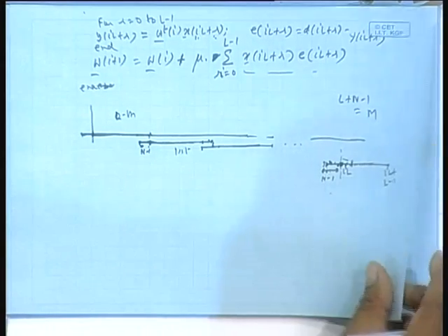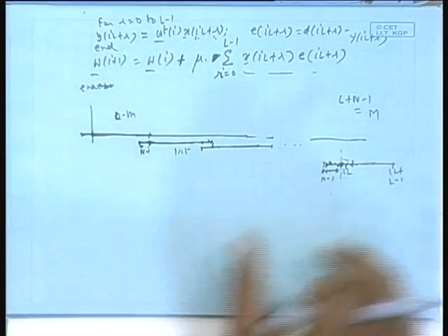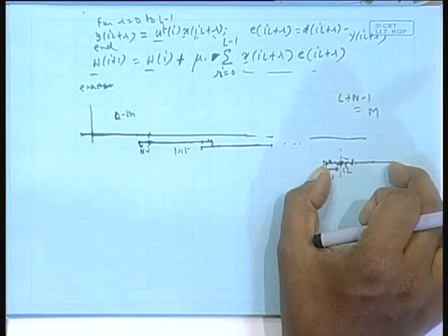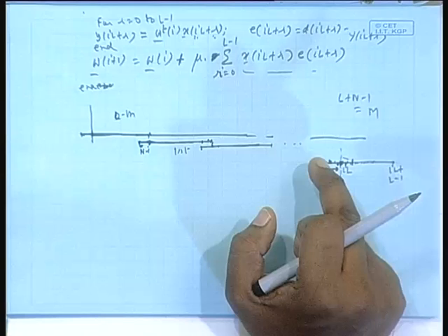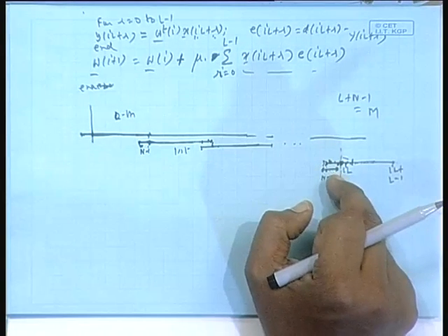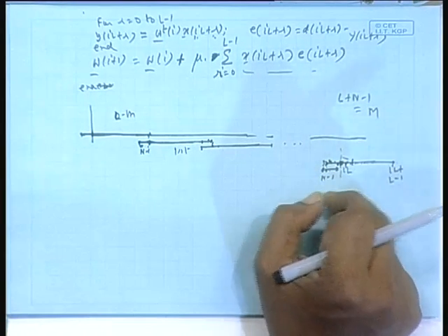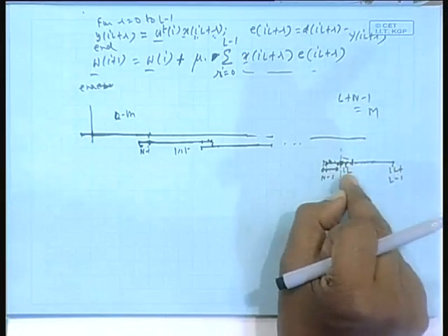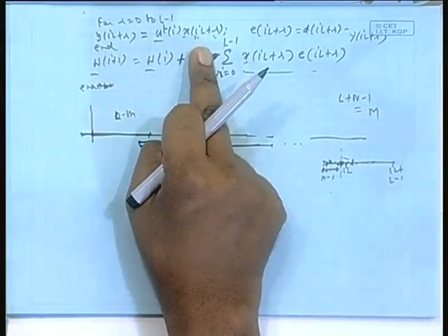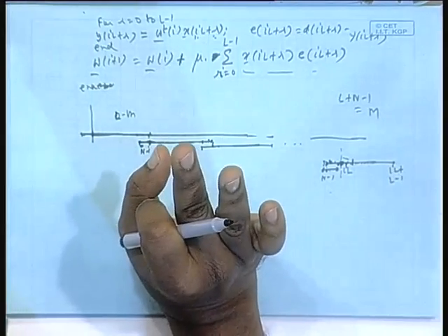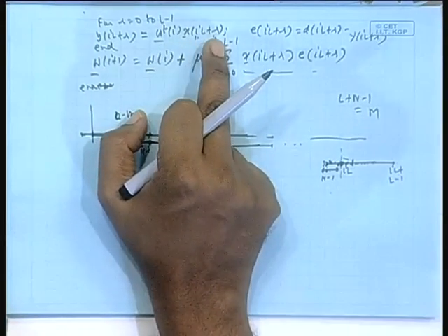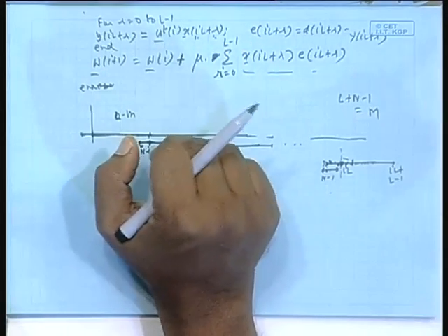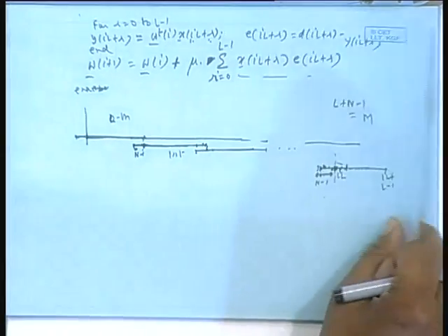So, that means both for weight update and all, this one chunk of data, one block of data is enough for me. In the filtering part, I will do a circular convolution by FFT, but I will throw away the first n minus 1 samples. Then from the ILth point onwards, circular convolution-wise also I will get the correct result as given by this equation, isn't it? This is the convolution at IL plus 0, IL plus 1, at those points. Okay.